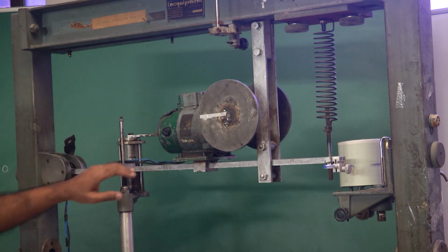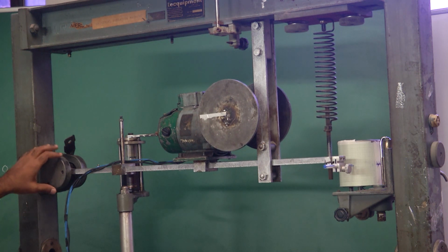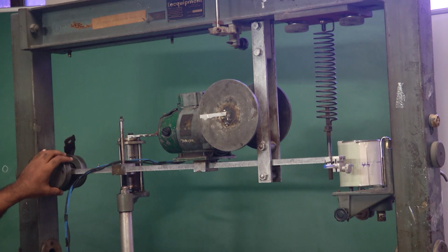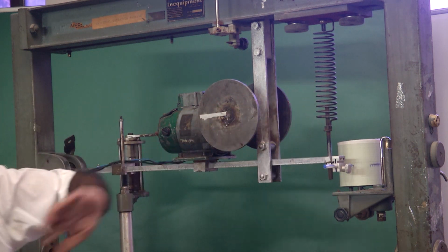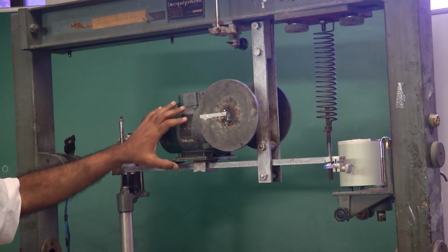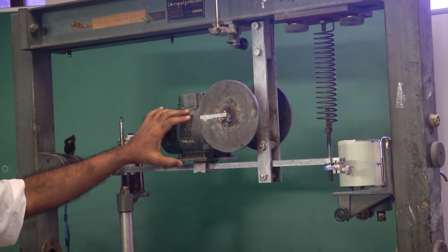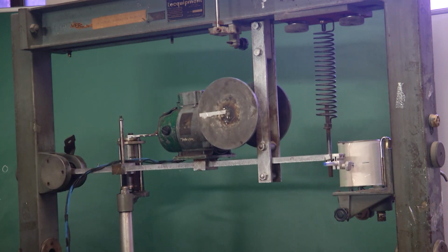This could be friction damping, because there is relative motion. Depending upon how lubricated it is, there would be either viscous damping, or Coulomb damping if there is metal to metal contact. So, this is one source, structural damping is the other one, and based on the shape and size of this motor, as it keeps swinging back and forth, you may also have very little aerodynamic damping as well.